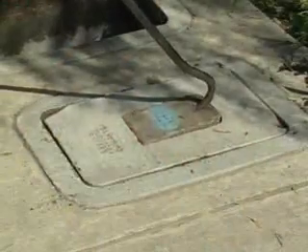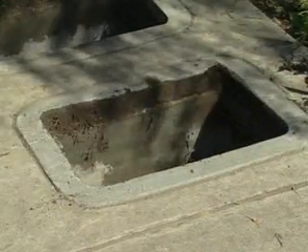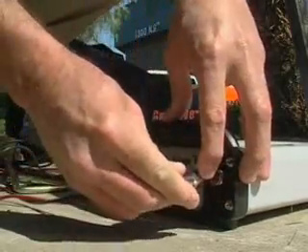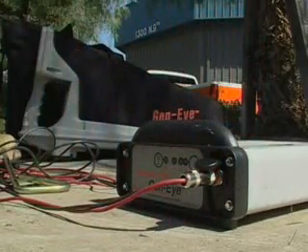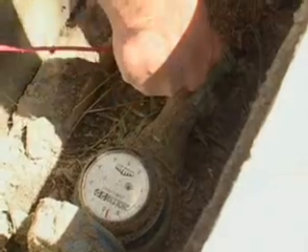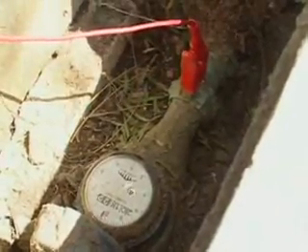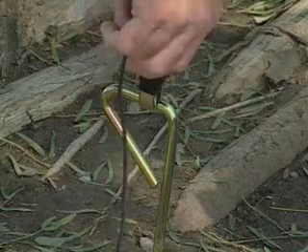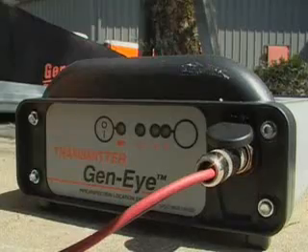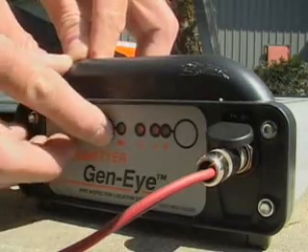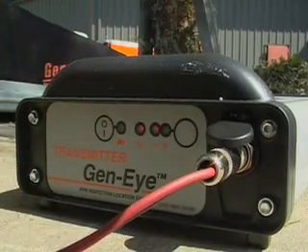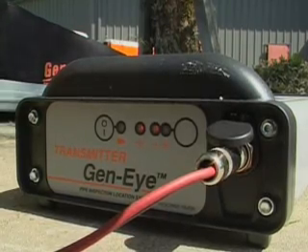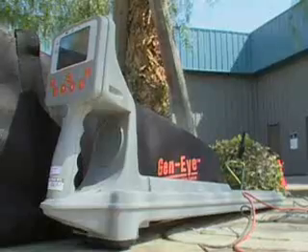To accurately pinpoint the leak, you must have an accurate location of the pipeline. You can locate the route of the water line by using General's Gen-I pipe locator and transmitter. Attach the red transmitter lead to the metal pipe and the black lead to the ground stake. Place the ground stake at least 3 feet away from the pipe. Press the power button on the transmitter 3 times so that the pipe location indicator flashes. If it does not flash, you do not have a good circuit. Recheck the connections.